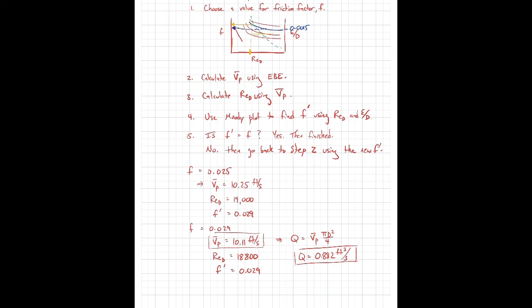One way to think about that is, I don't know if you've had experience with the Newton-Raphson method for iterating to a solution in root solving for equations, but there are some conditions under which that Newton-Raphson technique will not converge. So it's possible that we may run into a situation where it doesn't converge. If you come across a situation like that, first thing you ought to do is try a different initial guess to see if you can get it to converge for a different guess. Very likely when you solve these pipe system problems, you're not going to run into those problems, but I just want you to be aware of it.